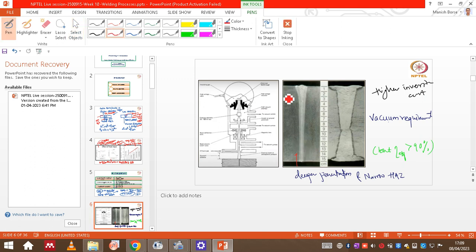Okay, so this is a typical macrograph of a joint made by electron beam welding. We can see a much thicker plate, like a 15 centimeter plate, welded in a single pass, whereas multiple passes are needed to weld this much thicker plate with the conventional GMAW process, right? So this right hand side is for the GMAW process.